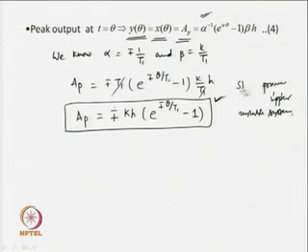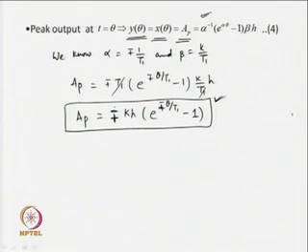So, for an unstable first order plus dead time model, we shall go for the lower symbols, plus here and plus here, but for a stable first order plus dead time transfer function model, we have to use the upper symbol, minus here and minus here.